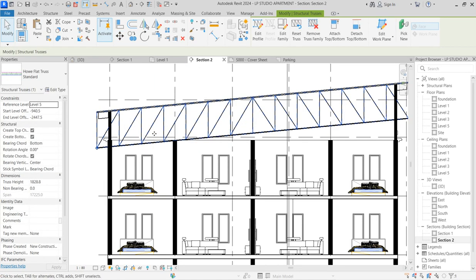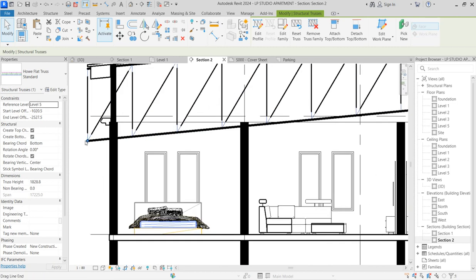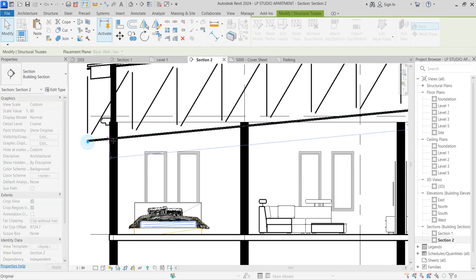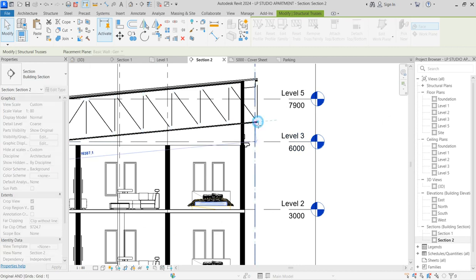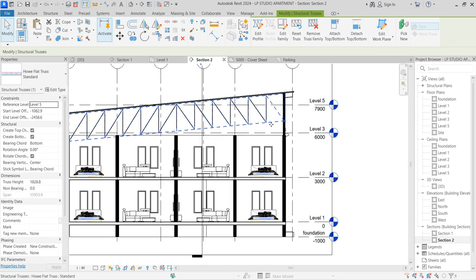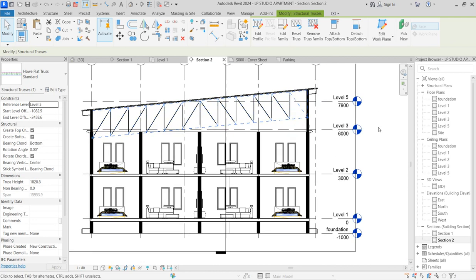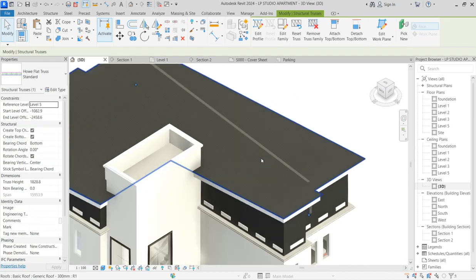And you see, so there, adjust by pressing arrow key. So you can make it a little lower than what you have here, update, and the same thing, then bring it here and update. So this is the structural part which you have created. It's not the end to what you have done here yet. So as we have done with this one now, you can go to 3D and check what you brought to this place, whether it's right or not.